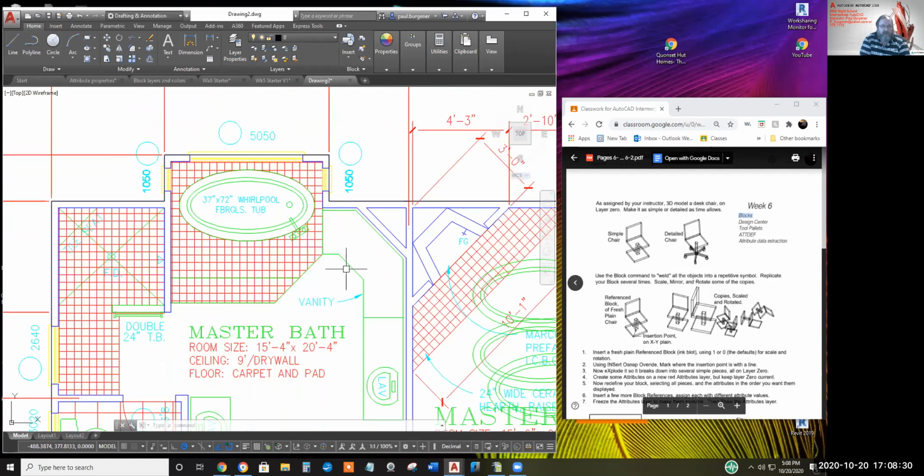Those of you that just tuned in, nesting means you create a block out of a bunch of blocks. And then maybe you got a bunch of these mega blocks, you use them all and weld them into a super block. So you need to explode the super block to get it down to the mega blocks, and then explode the mega blocks to get into the individual blocks, and then explode the individual blocks to get down to the lines, arcs, and circles.